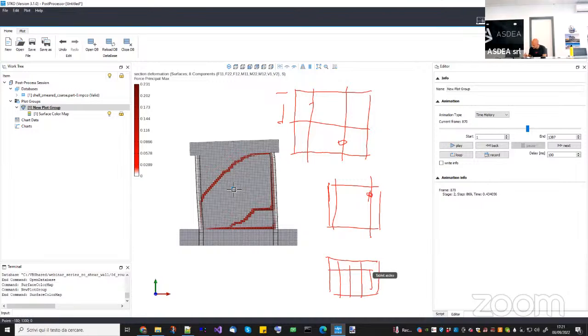Now, each one of my finite elements, at its integration point, will have another contribution of steel with a smaller area, but this one will be basically equivalent to having a lot of rebars, many rebars, with a very tiny area. So as you keep on refining the mesh, you tend to a homogeneous material, but actually in reality, the material is not homogeneous. So this is one of the problems that you have with strain softening.